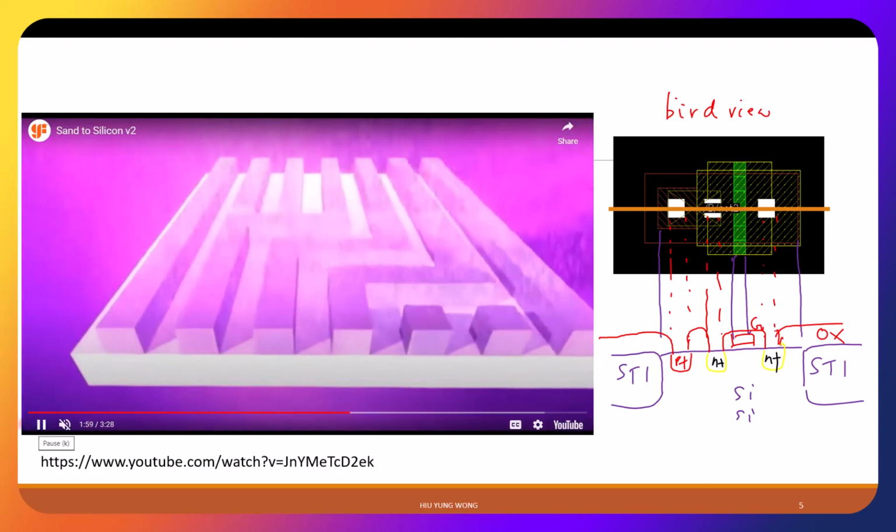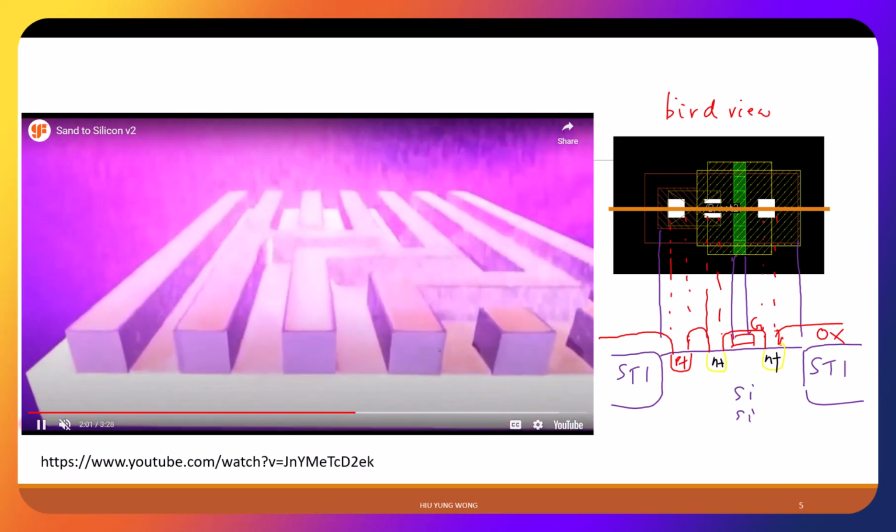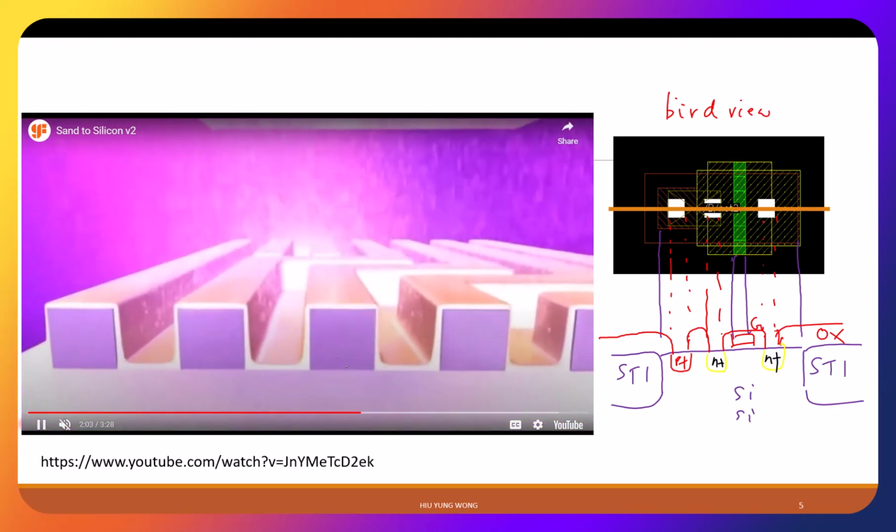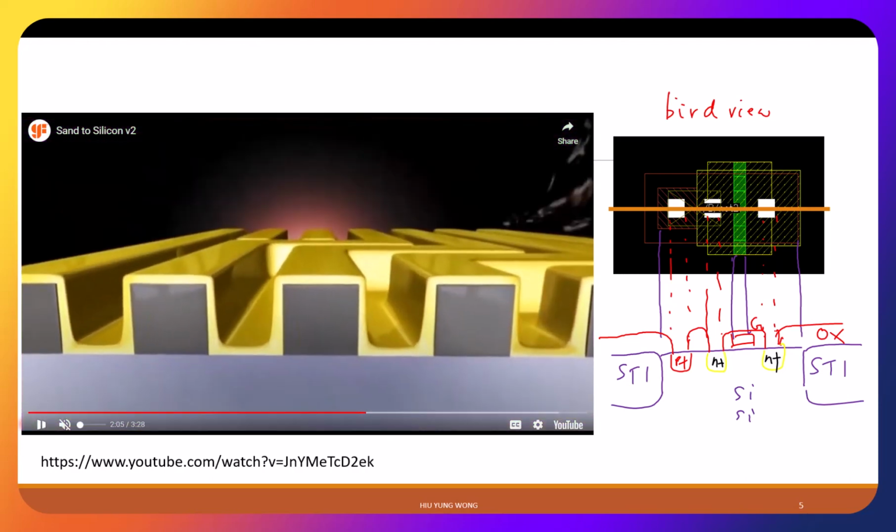Well, right. This is another step already. Look at it. It forms a layer, right? It can be so-called atomic layer deposition. Nowadays the technology is so good. Applied Materials, Lam Research, they produce this tool. They deposit layers of atoms, very well controlled. So this is not doing implantation. You see they deposit conformally. This is the key word, right?